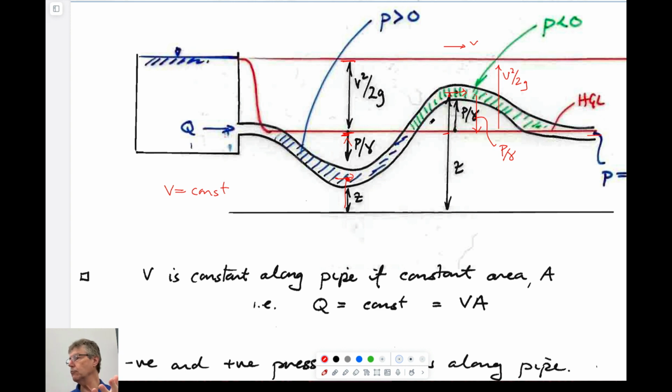So air will dissolve in water under normal atmospheric pressure because it's being pushed in there by 101 kPa. And so if you want to get that dissolved air out of the system, you put it in a vacuum. So you put it in a container and put a vacuum on it, or you could just run it along a pipe horizontally. And if you take that pipe so that it's 30 feet up, about 10 meters, then because 10 meters of head is 101 kPa, then it goes through the vapor pressure of water.